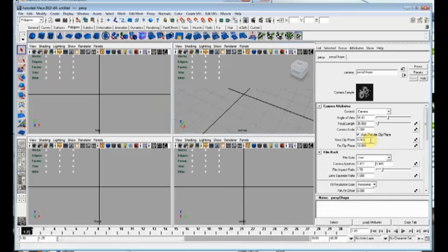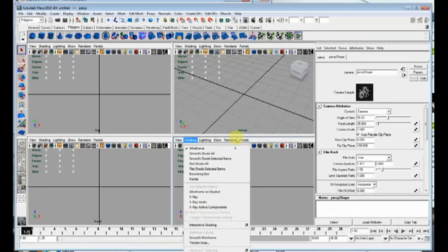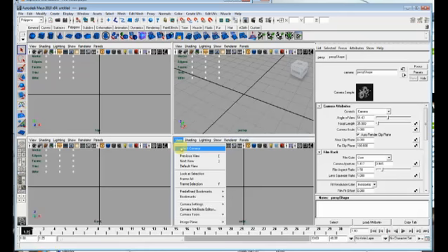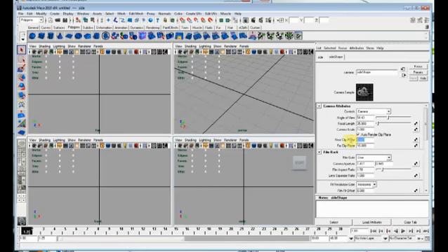And the units are expressed in meters. So you want to keep the near clip plane to, let's say, 1/10 of a millimeter. And you want to keep your far clip plane, let's see, how big are we making? Let's say it's an airplane, 100 meters. And you hit Tab. Now you go down with the Control A still open. You hit Select Camera on each view, and you do the same thing.